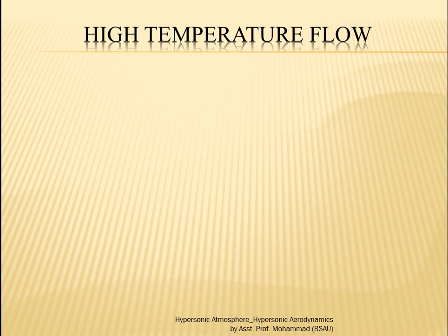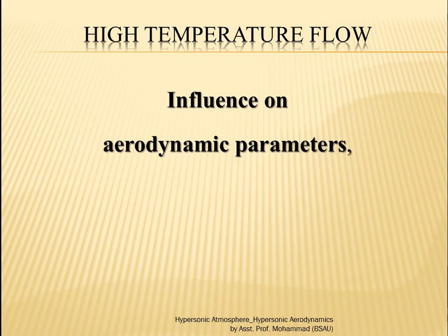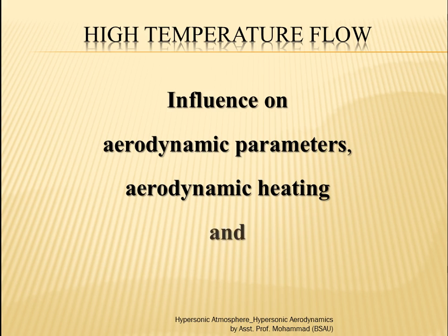Now there are some consequences of the presence of high temperature reacting fluid or plasma in the vicinity of the flight vehicle. They are influence on aerodynamic parameters, aerodynamic heating, and communication blackout. Flight parameters like pitch, roll, drag, and deflection of control surfaces normally get affected, and the deflection gets deviated heavily, and unusual estimates come because of the calorically perfect gas assumption, which is not valid because of the high temperature.